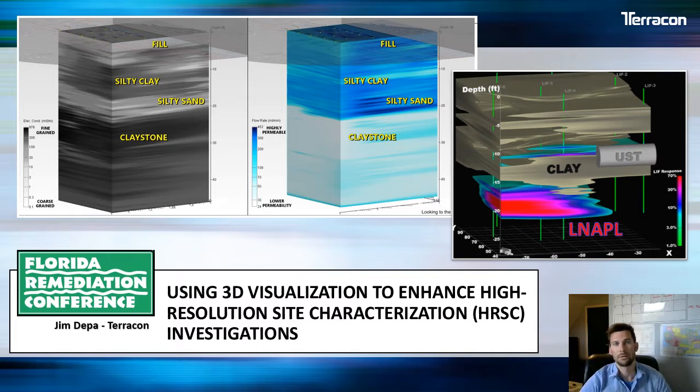I'm going to speak about using 3D visualizations to enhance high-resolution site characterization investigations. And you can see on the screen here, there's one from a dry cleaner where we used a hydraulic profiling tool to identify the geology of the site, and then another one in a LIF investigation where we found a great deal of LNAPL below a clay unit near a spilled UST.